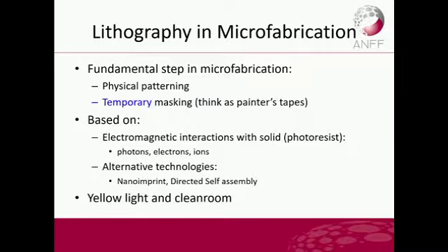You can either use it as a physical patterning method on a substrate, for example, you can mold your resist feature, like how you do it in PDMS soft lithography. Or you can use it as a temporary mask. And the term temporary is very important, because after you finish your lithography, after you etch and deposit your materials, you actually want to remove these materials so they don't leave any trace behind. Then you can continue on with your next lithography process.